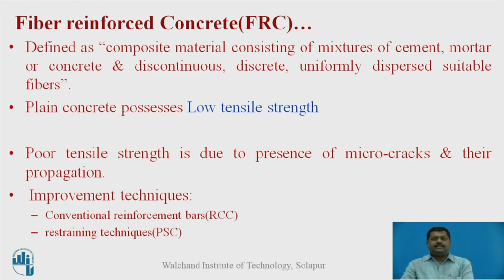Now, how can this tensile strength of concrete be improved? One is the conventional method: conventional reinforcement or reinforcing bars can be introduced in the concrete. So that is our regular RCC. And second, tensile strength can be improved by introducing tendons into the concrete, and that is pre-stressed concrete. But these are techniques to improve the tensile strength of the section, not of the concrete. So concrete will remain as it is, which is brittle in nature.